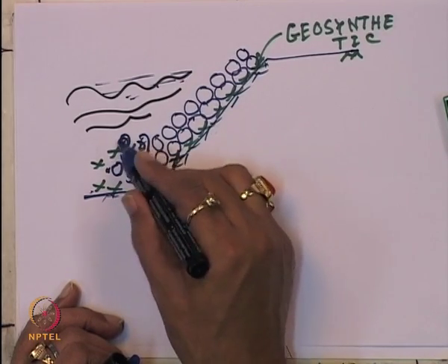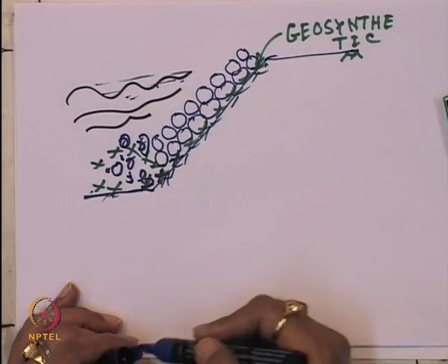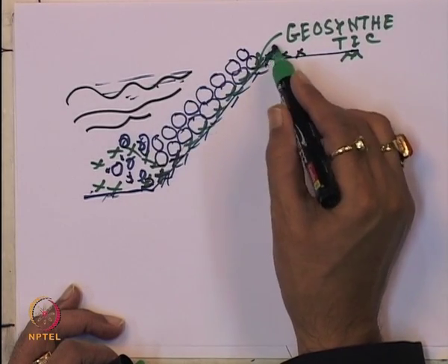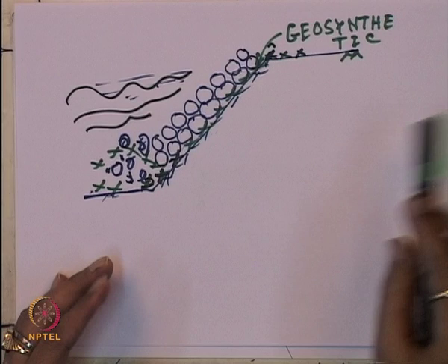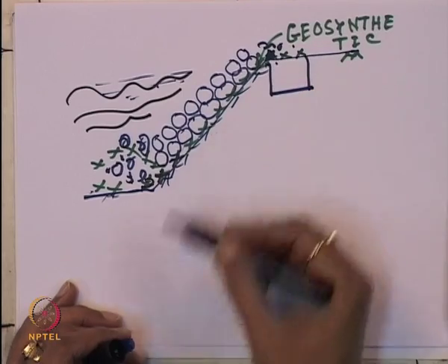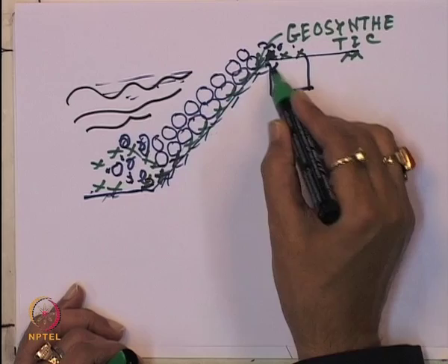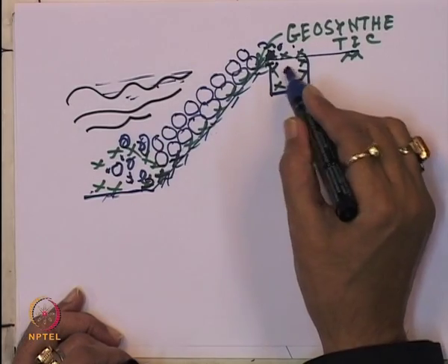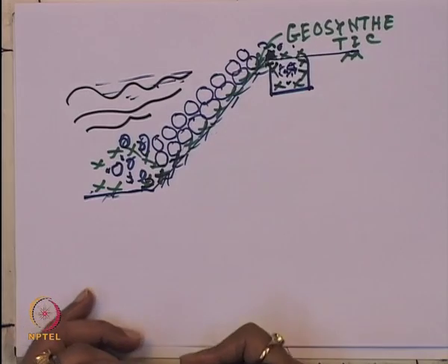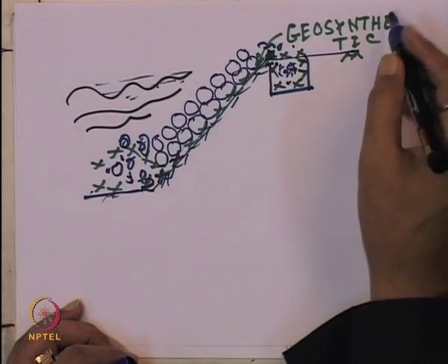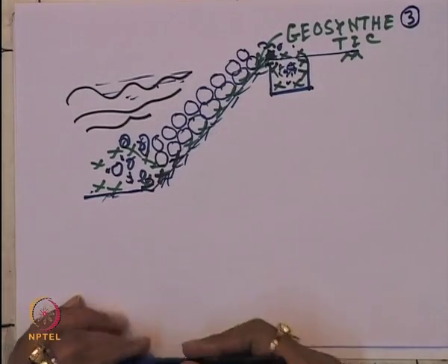Okay, you can put it on the top, so it can act as an anchor, and similarly on the top side also you can place the geotextile material, then you can place this armor stone like this, or you can make a trench also, where this geotextile material can be placed and covered like this, and it can be filled up with the aggregate, okay, to make it stable. So you can see how this geosynthetic material can be used for erosion control.